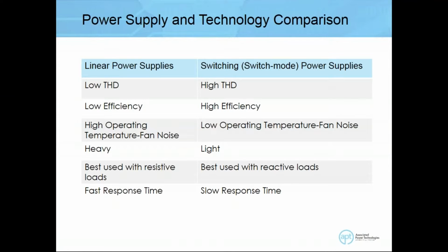It does have a slow response time. Since we're doing a lot of signal modification, we're taking the signal and doing pulse width modulation to make it into a square wave, and the square wave is then filtered out at the output. There is some response time for converting the energy from input to output because it goes through these phases.